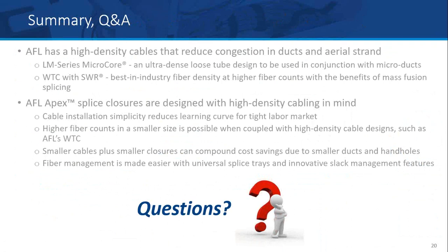So what you've got to do is take into account the length of the closure plus the bend radius of the cable. So you've got your closure in there, and hopefully everybody can see me, I'm waving my hands. So you've got that bend radius that sweeps off the back of that butt entry closure. So that bend radius plus the length of the closure would accommodate a 24-inch long vault, 12 by 24. You just got to make sure it's married up with the right fiber count.